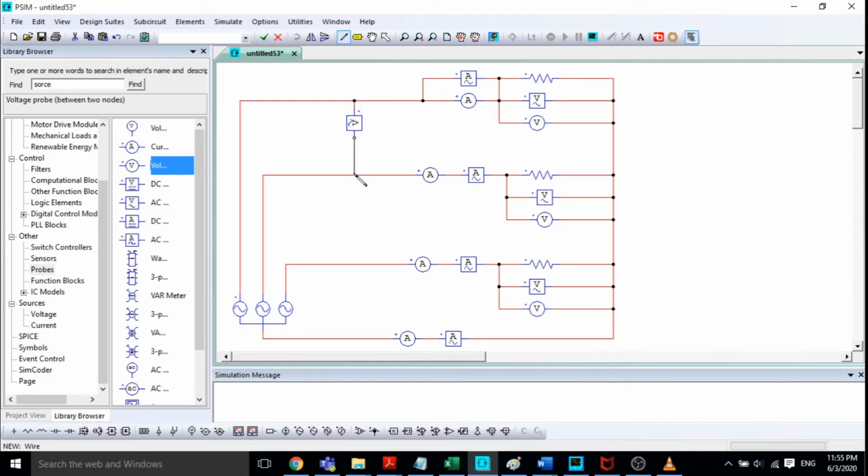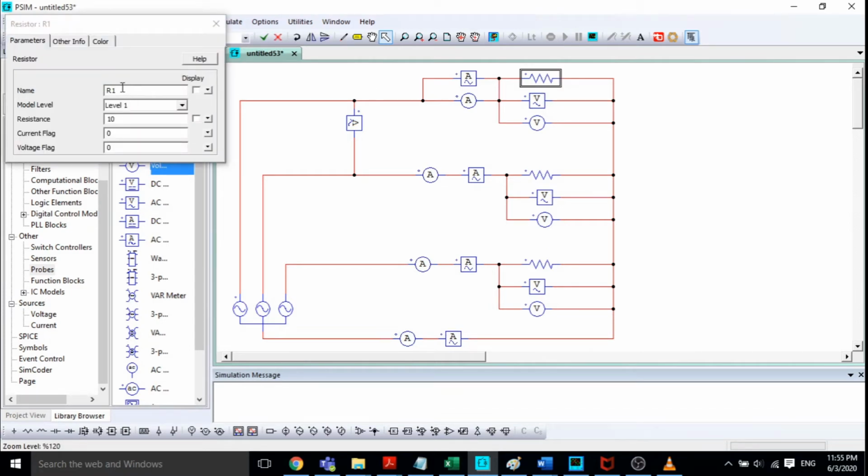Mistakes do happen, so whenever you finish the circuit, make sure you check out everything. So now I'm going to start naming the resistors. So this is going to be R1, the value is going to be 200 ohms. For resistors and all components like this in particular, I like to show their name and show their value, name or reference. So this is R3, 200 ohms. So we check that out.